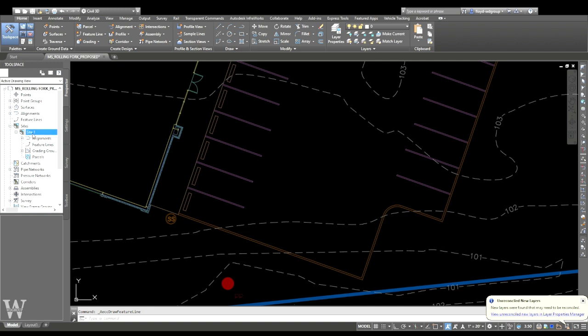So what I haven't done is I haven't taken this drawing and cleaned it up. Basically, I'll go in and delete out the sites that's there, and then I'm going to make sure my data shortcuts are set in the right place. I have the right surface in here because it was set up by somebody else, but they didn't set up the data shortcut folder, which doesn't matter right this minute, but I'm going to set it up sooner or later.